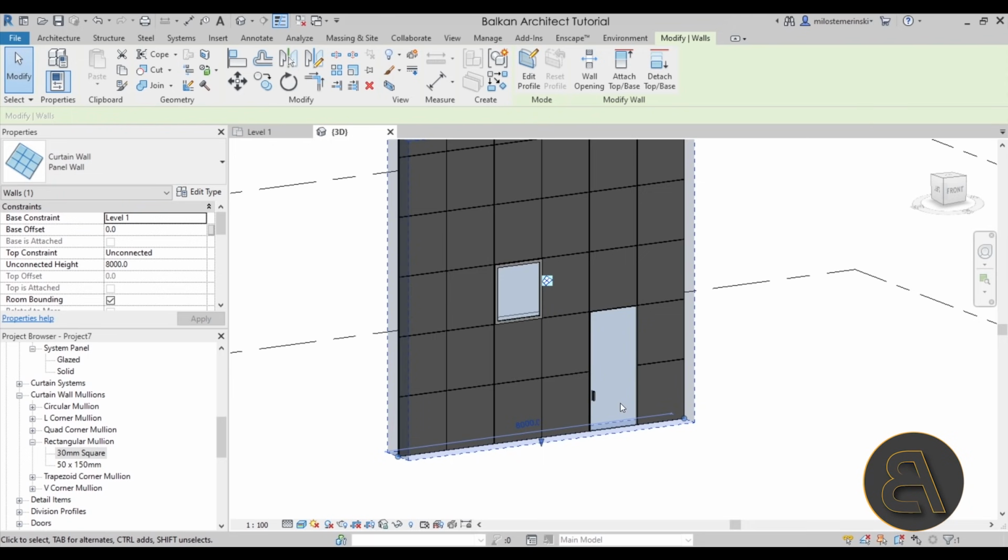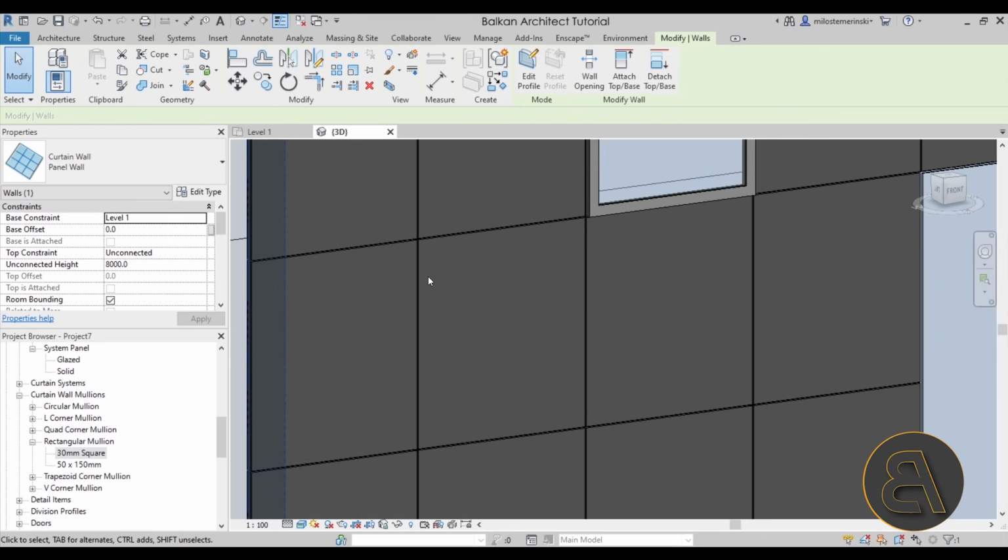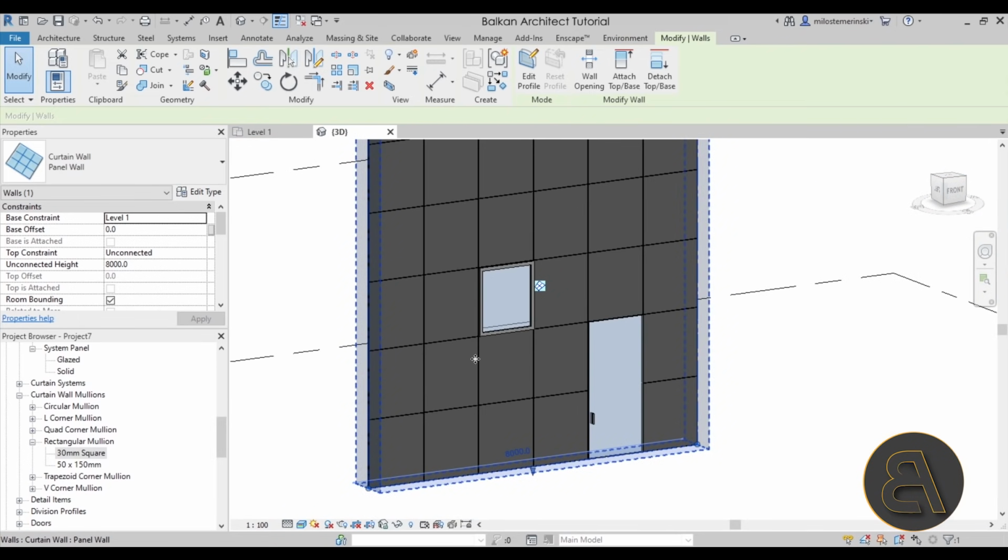It's really versatile. It's really cool. It takes perhaps a little bit longer to set up, but I think the trade-off is definitely worth it. Now, obviously, you can do many more things. You can get rid of the mullions completely, and then create a customized panel that would work with a little gap on each side. So there's many different approaches, but in the end, I think this is probably the best approach when it comes to creating these panel facades, because it does give you the most versatility and the biggest ability for changing the pattern later on in the project.